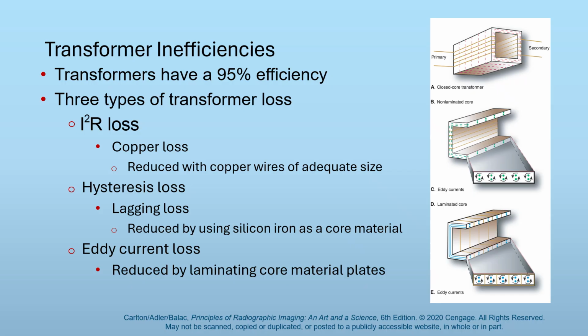And so you'll get some that are, for whatever reason, because it is a quantum effect, delayed in flipping, and so their neighbors will be delayed in flipping. And yeah, you'll have some domains that struggle to flip exactly at 60 hertz. Okay, if we space out the iron into tiny particles like iron dust in silicon, then we can reduce the number of neighbors, and then we can reduce the lag, reduce those stubborn domains.